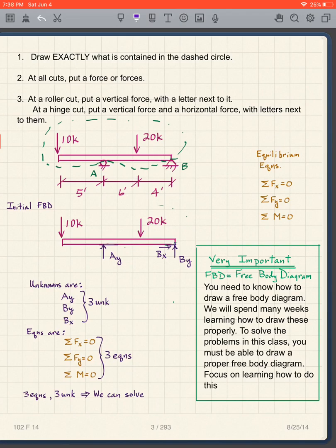So now notice, the sum of the forces are 0. For instance, why are the sum of the forces 0? Because something is not moving. Now we have to pay attention to signs, such that up and down, we're going to call up positive, down negative. Another way to look at it is the sum of the forces going up equals the sum of the forces going down. But if we assign positive and negative signs to them, then the sum of the forces is 0. Same thing, right and left. The sum of the forces going to the right equals the sum of the forces going to the left. We'll say that the forces going right are positive, the forces going left are negative, and since we're assigning signs to those, we find that the sum of the forces is 0.